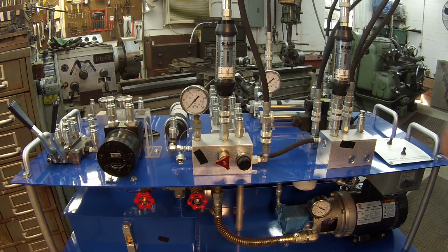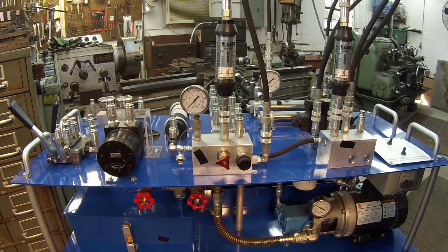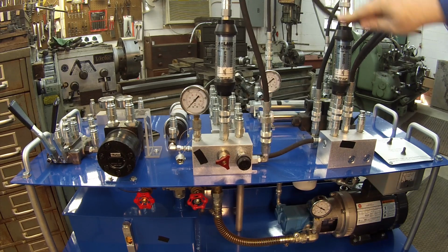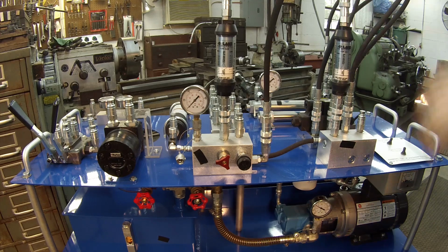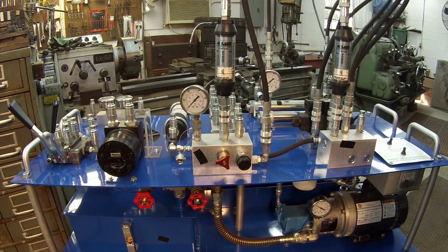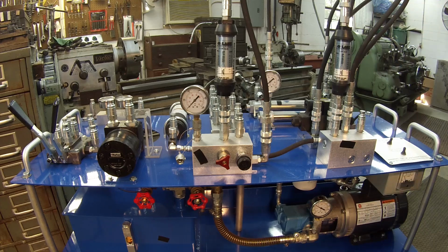Another one is not being supported properly. You have to have pipe and hose clamps and supports in your hydraulic system, or these things will start rubbing together like this, and you don't want that because they'll start fracturing. That's the number one cause of safety problems in hydraulics: slips, trips, falls, and oil injection. If you have a hose rubbing on another one and it starts spraying, and you walk up there and touch it with your finger, you'll get injected with oil. We'll talk about that in the safety part.